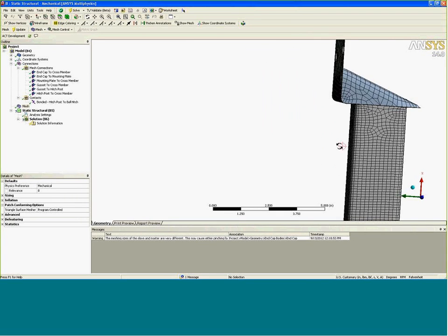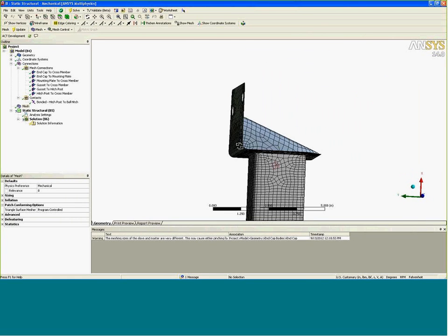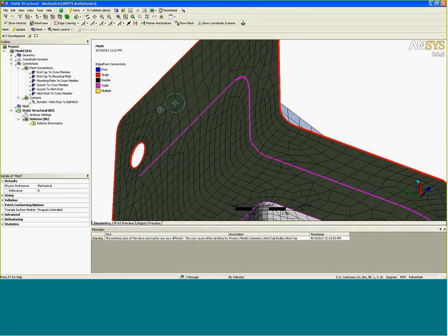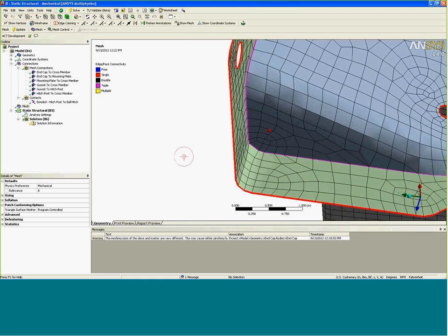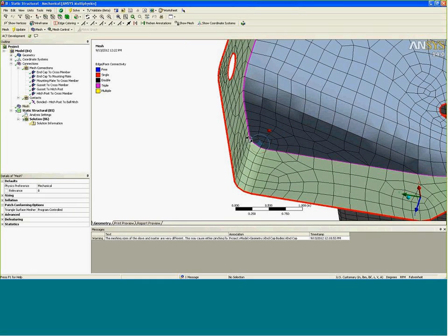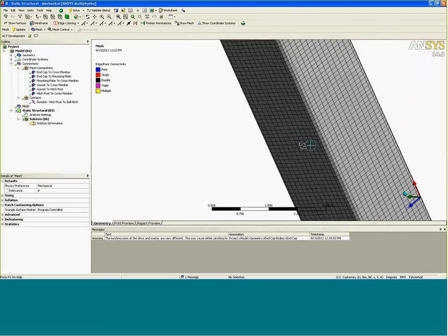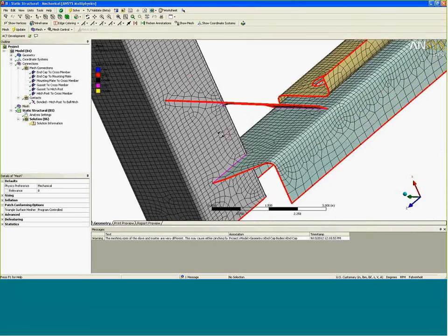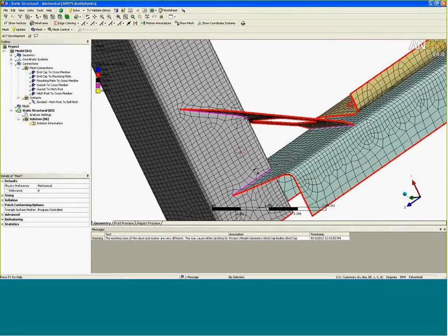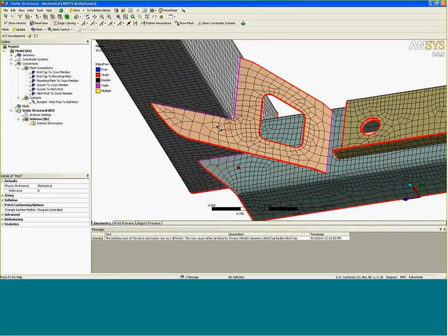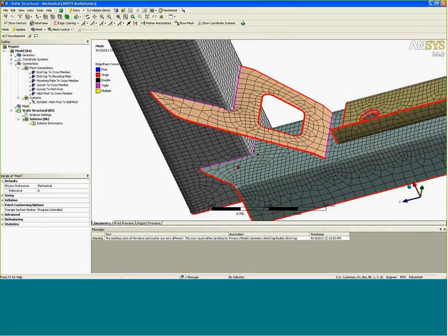So at this location here, it's maybe a little bit easier to see if I turn on the edge coloring in here. These edges here are triples. So this surface, and the surface that's up here, those are all connected at the mesh level. Like the same thing. If we look here, we can move this back down here. There we go. You can see that those are connected with the coloring.